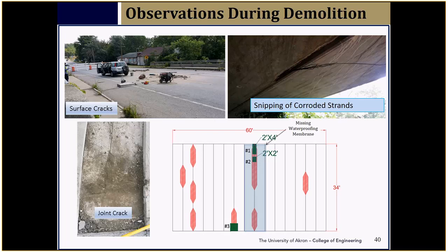I'm not sure, but what's happening is the temperature can cause a significant amount of longitudinal movement between adjacent beams. That's a problem, which is one of the causes for cracking of the joint.